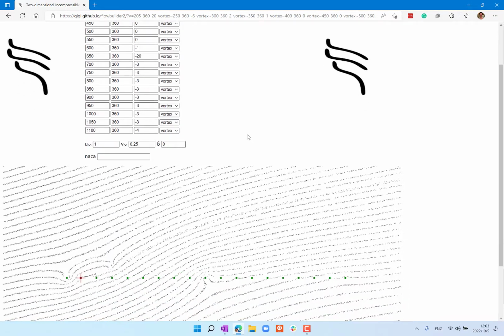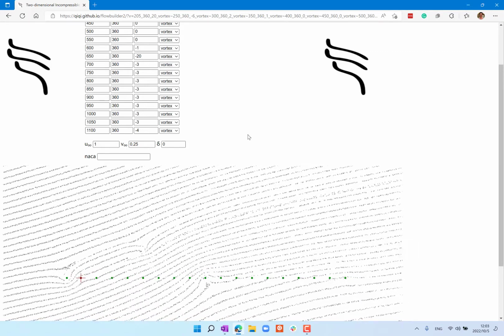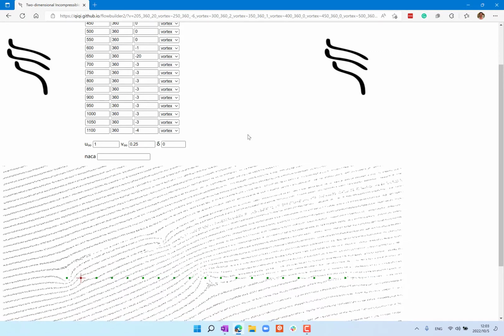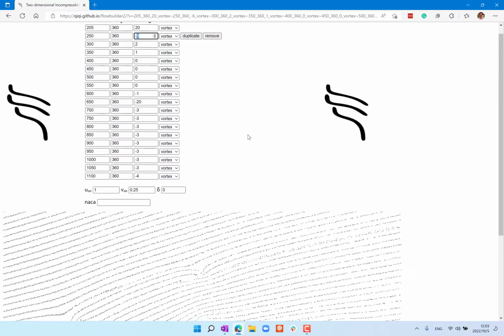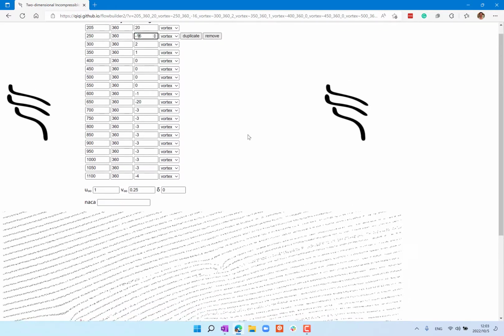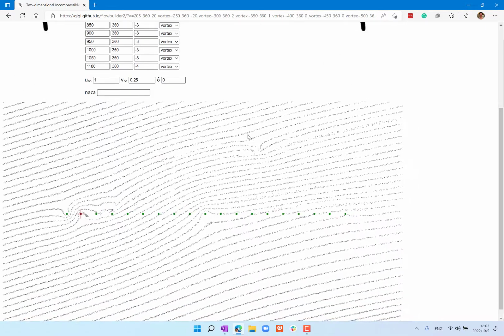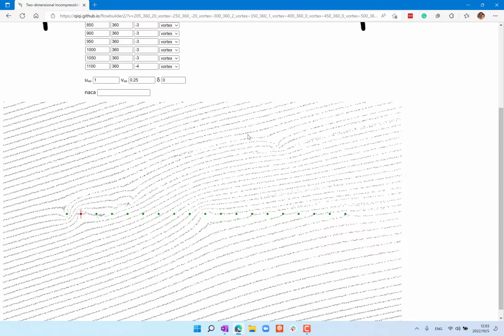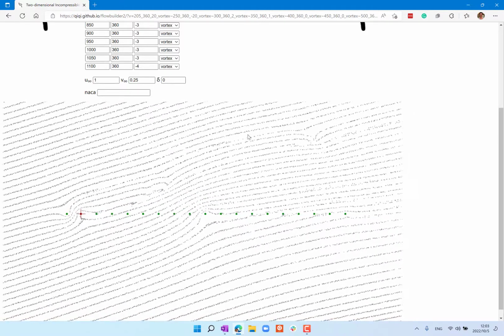Now you're going to see it's a little bit better downstream of here. The flow is no longer going through the flat plate at such a high y velocity, so maybe go even higher, minus 16, or let's just make it minus 20. Now you're going to see that at least locally, the flow goes more parallel to the flat plate.